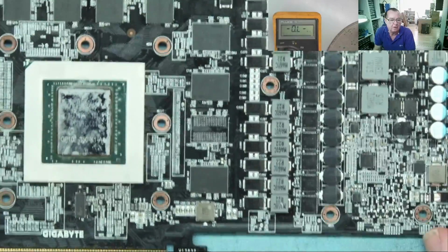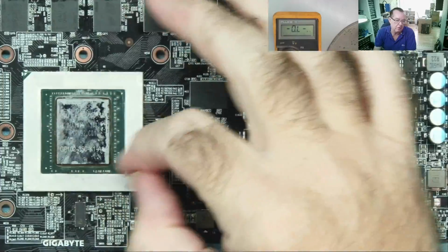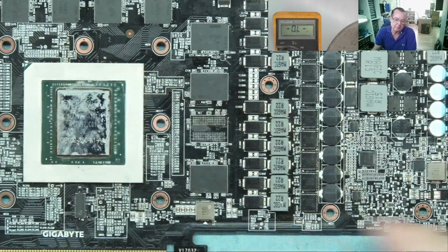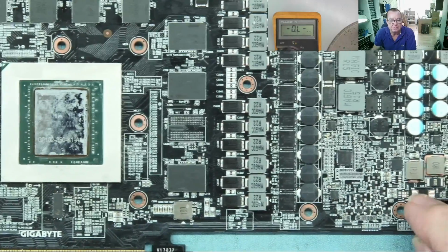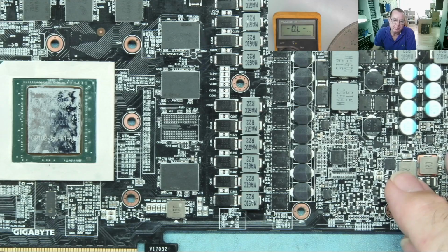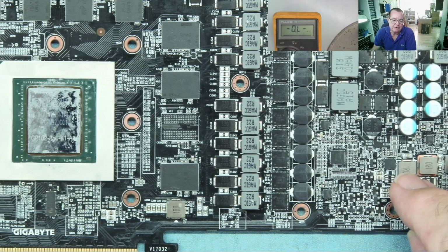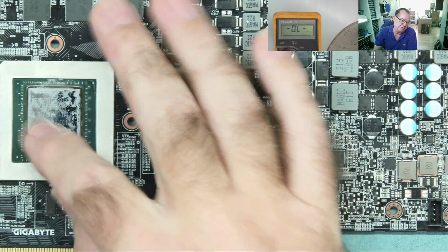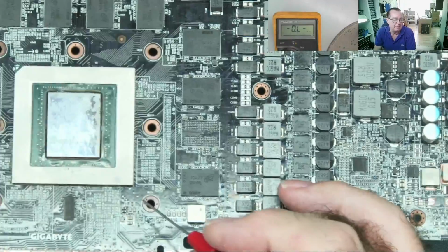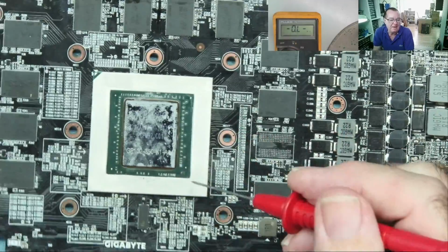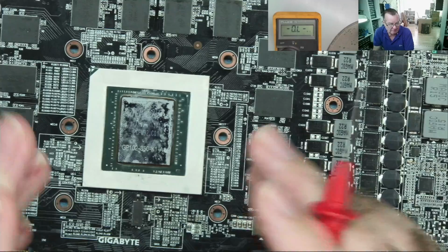So on this graphics card, we know we have short circuit V-core. Where does it go to? The GPU. We have short circuit PEX. Where does it go to? The GPU. And we have a short circuit on this one here as well. Quite probably the 1.8. It's going to be one of the other voltages, yeah. Maybe this one is the memory controller because these both seem to connect together as RAM. But there's a short circuit on it, and I think we can say confidently that goes to the GPU. So all this, as well as the fact that this is bubbled, all these readings are telling us we have a faulty GPU. Even if it visibly looked okay, we have a faulty GPU.